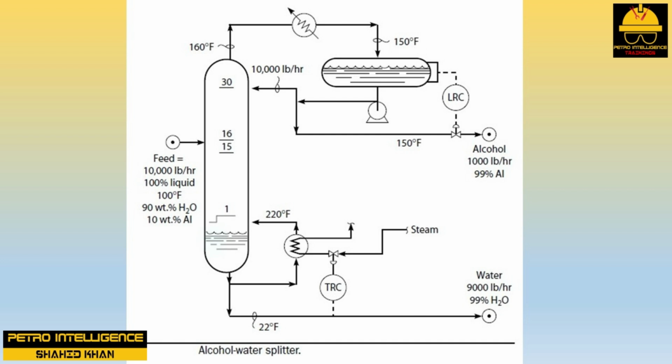The statement that the mass, or weight flow of vapor through the trays, increases as the reflux rate is raised is based on the reboiler being on automatic temperature control. If the reboiler were on manual control, then the flow of steam and the reboiler heat duty would remain constant as the reflux rate was increased, and the weight flow of vapor up the tower would remain constant as the top reflux rate was increased. But the liquid level in the reflux drum would begin to drop. The reflux drum level recorder controller, LRC, would close off to catch the falling level, and the overhead product rate would drop in proportion to the increase in reflux rate.